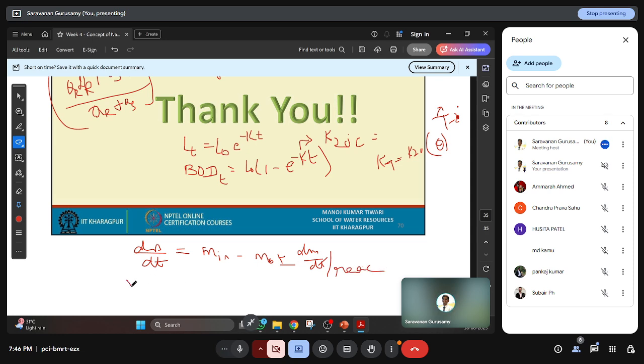If you substitute with the volume, because we need a controlled volume, V dC by dt equals Q C in minus Q C out plus or minus V into, if it's a first order reaction, k C power n. You got it? Based on the conditions, if it is steady state, the left side will become 0. If it's conservative, the reaction term on the right side will become 0. If it's a batch reactor, in and out will become 0.